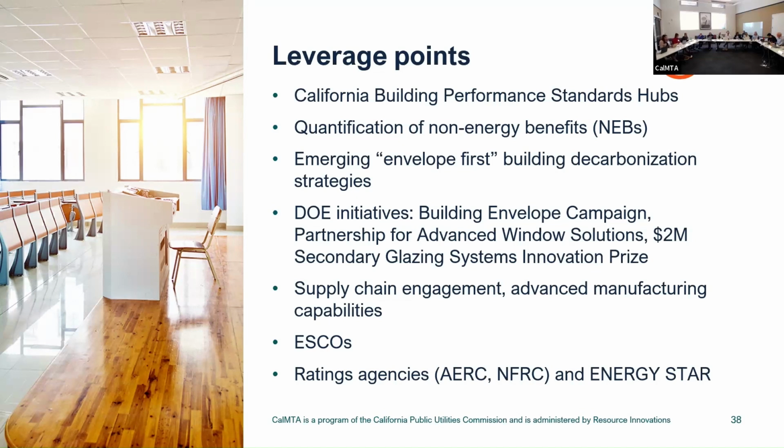Emerging envelope first building decarbonization strategies through the hubs, through DOE, through Local Law 97, through RMI, New Buildings Institute. We're seeing them recognize the importance of envelope first strategies as they help building owners navigate building performance standards. It's very different if you just want to make your building more efficient versus if you have a target to hit. If you have a target to hit, that's very different than saying, I'm just going to do the low hanging fruit.